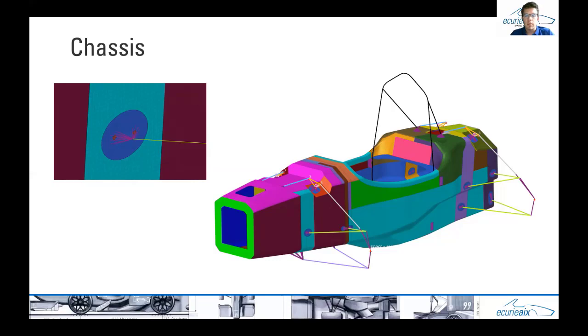We are doing this because when we have a good torsional stiffness, which we simulate in the beginning to see how much we need, we can be sure that there's also a sufficiently good bending stiffness, so that we can set up our setup quite well.